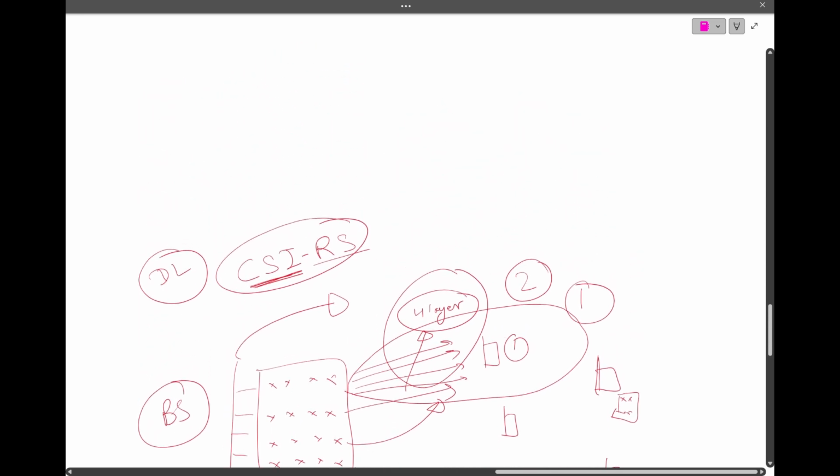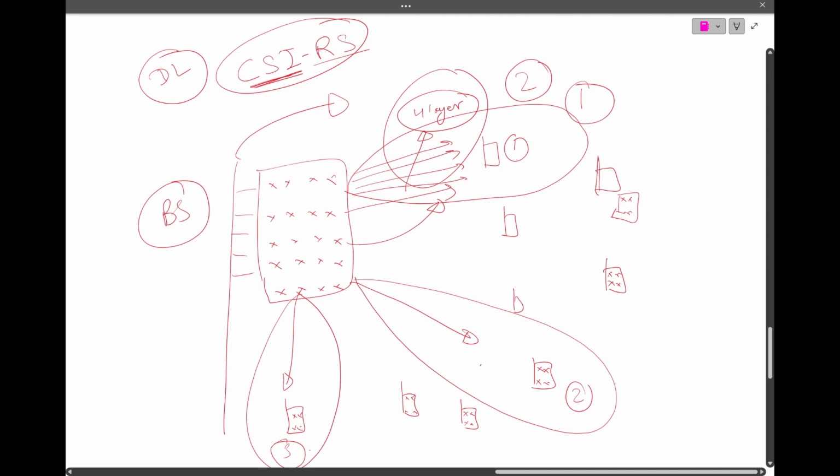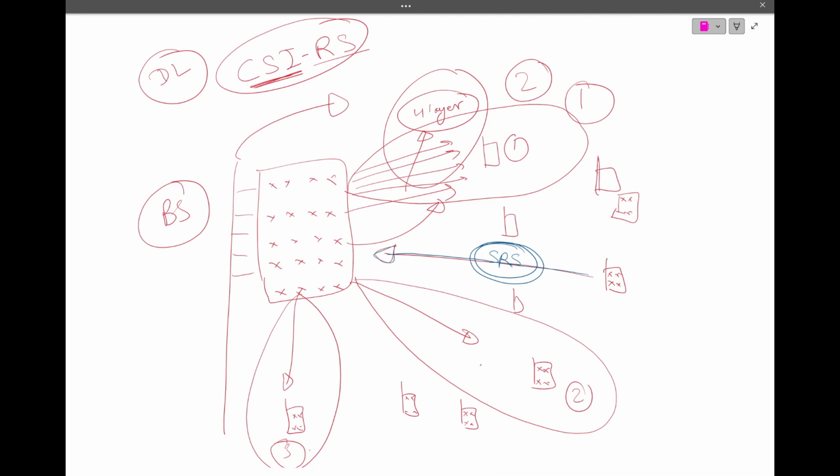Similarly, there are signals for the same purpose transmitted from UE to base station. These signals are called SRS, sounding reference signals. They help the base station find out the channel between UE and base station for uplink signal transmissions. It finds out how many parallel streams that particular cell phone can send in uplink, and what resources work best for that particular UE.